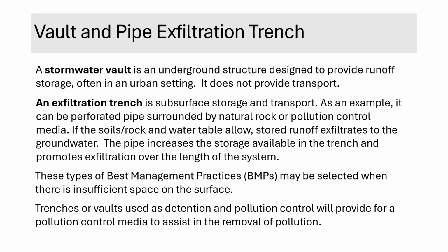In contrast, a stormwater vault is primarily an underground structure built to provide runoff storage, particularly common in urban environments where surface space is at a premium. A key distinction here is that while a vault stores runoff, it does not provide for the transport of that water in the same way a trench does. Both trenches and vaults can function as either detention or retention systems.